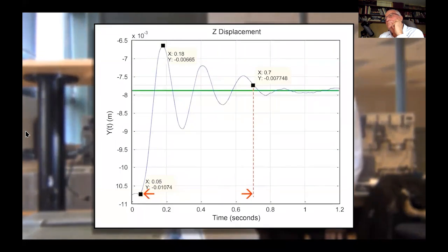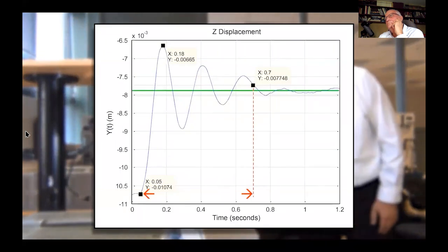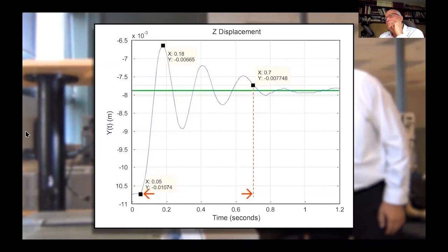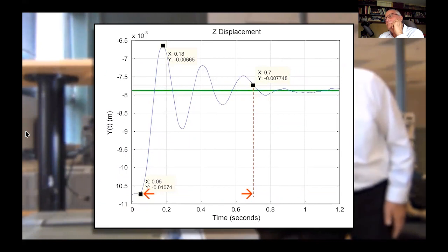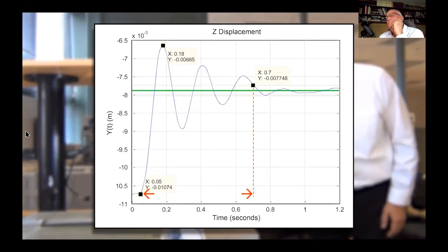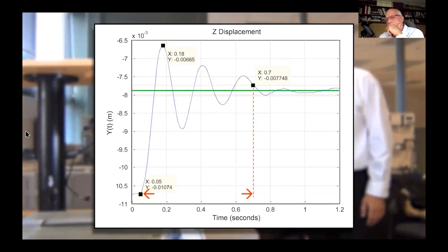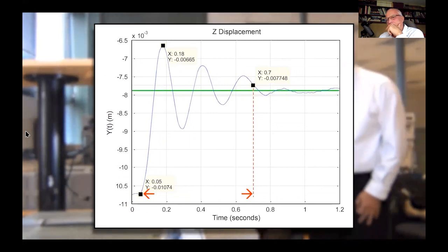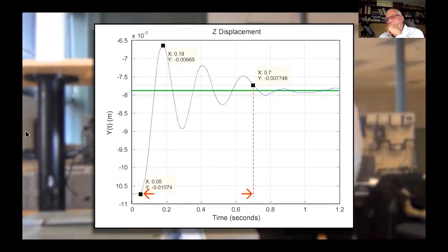If we do compare our compensator to a PID compensator, which has been optimized after many, many trials, we observe the following. Number one, the overshoot is quite important. Static error is small, but the settling time is quite big, 650 milliseconds. Therefore, our compensator performs much better.